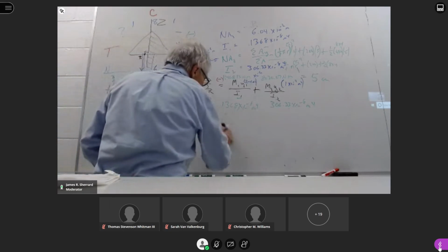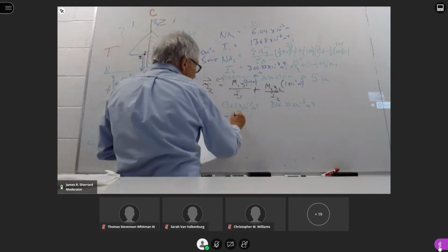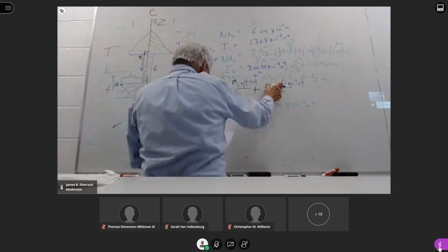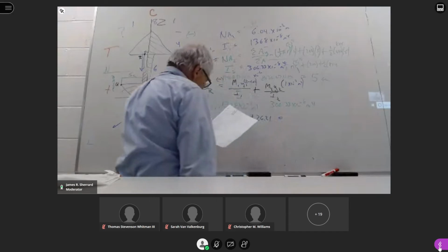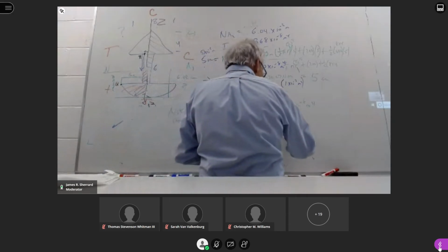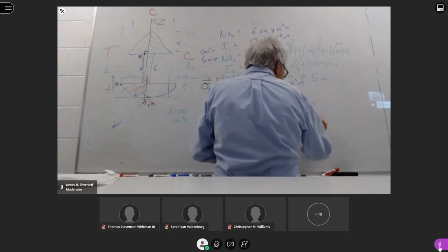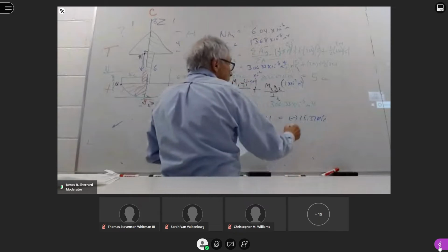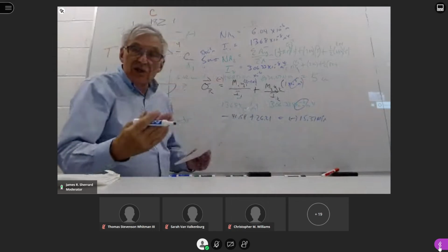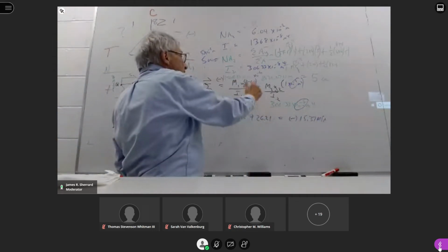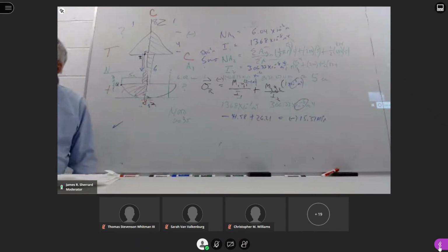I then do the math on this. I had this guy come out to be minus 41.58. This guy come out to be plus 26.21. So my net result is minus 15.37 megapascals, because again, 10 to the minus 2 divided by 10 to the minus 8 will give us 10 to the 6, which is mega. And then because we have everything in newtons and meters, it's going to come out pascals. Any questions on that?